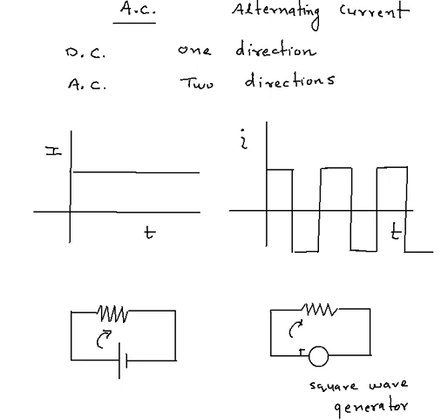However, when we were discussing LC circuit, that time you saw how current was changing its direction. In these examples, I have shown the magnitude flat. Look at this right side graph. I have shown it flat. It doesn't have to be flat. We have been talking about AC as current which changes direction. It can also change magnitude. So in fact, in reality, the current that we use is not flat, but it is variable. It is like a sine wave.